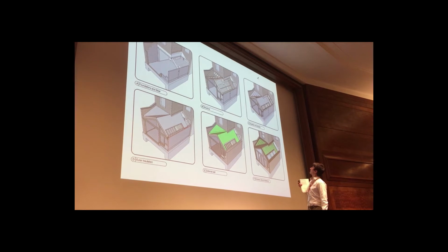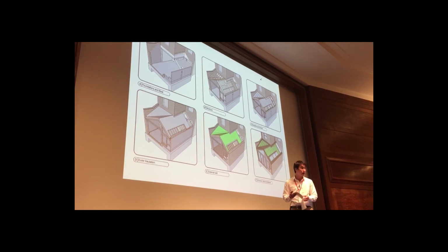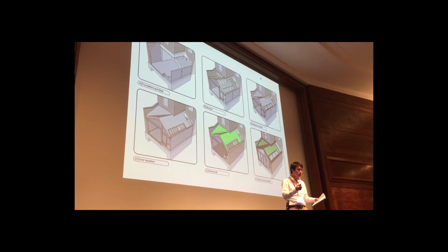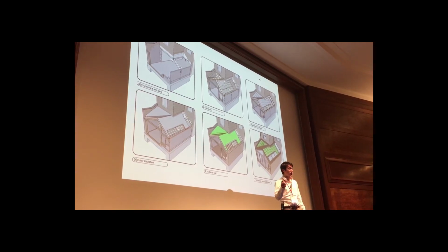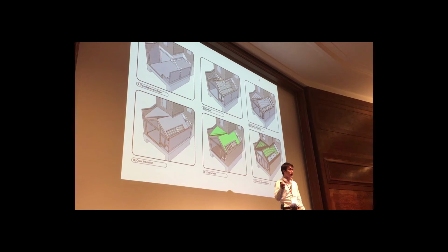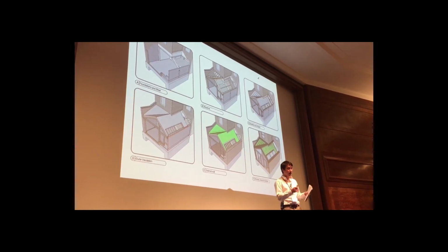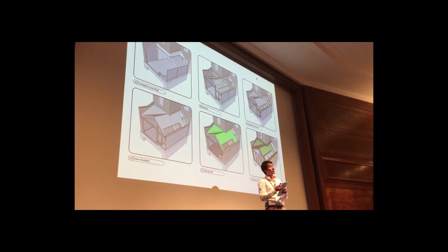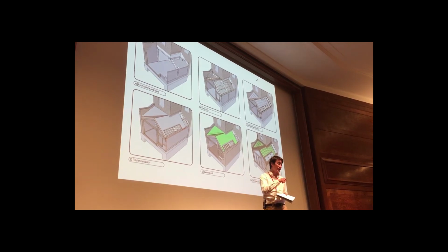it has everything in it. There are notable things that I do leave out. For instance, I leave out membranes. I don't do fixings like screws or bolts even. Joist hangers, I leave them out. Sheet materials are a bit difficult to model. So I make the judgment, I figure out what is actually going to be quicker.